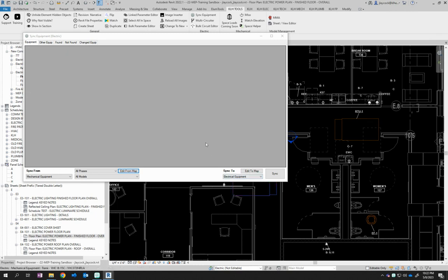The next thing you want to do is edit to map. So after what you first did was, again, map your parameters from your HVAC equipment, or the equipment that you're mapping to. From the equipment to the tool, the next thing that we're doing is gathering the parameters and moving that information from the equipment essentially to now your electrical connection family. So that could be either a piece of electrical equipment type, or it could be a fixture type. It kind of depends on how you have your family set up. So it's flexible to do either. For this one, I'm going to do electrical equipment, and it'll bring up all my electrical equipment options there when I'm mapping. And you'll see that next.